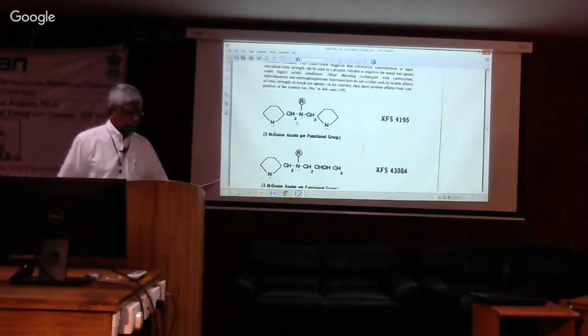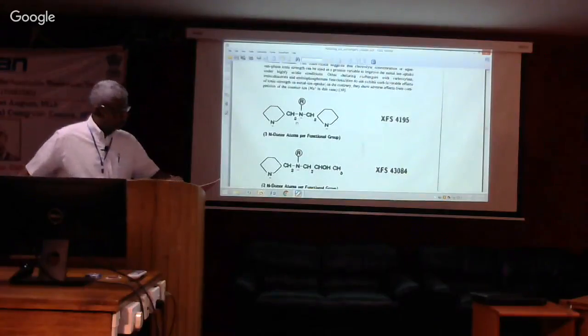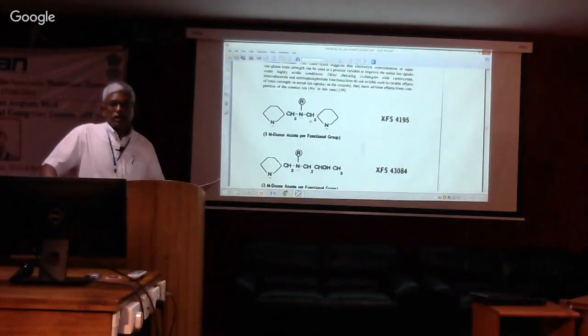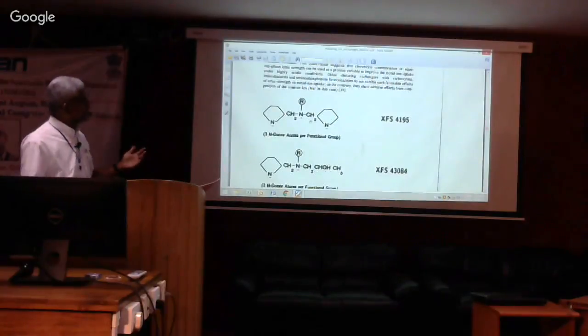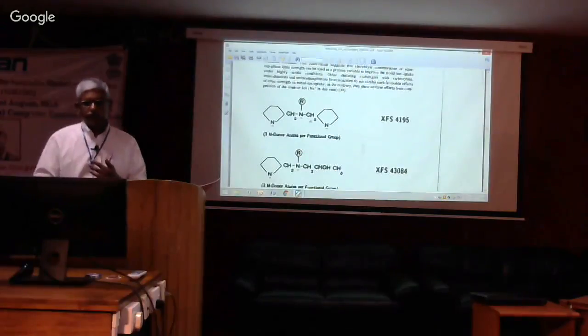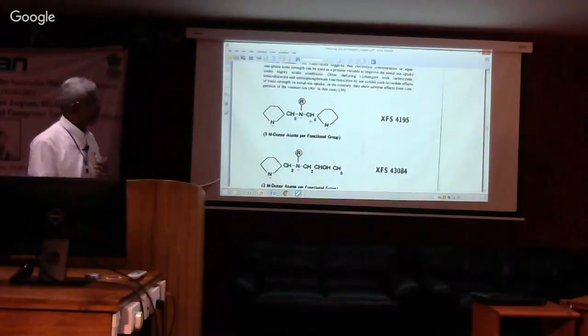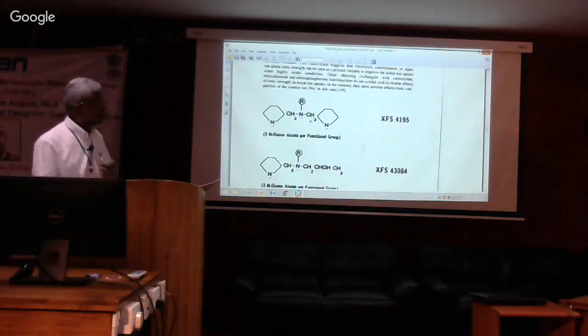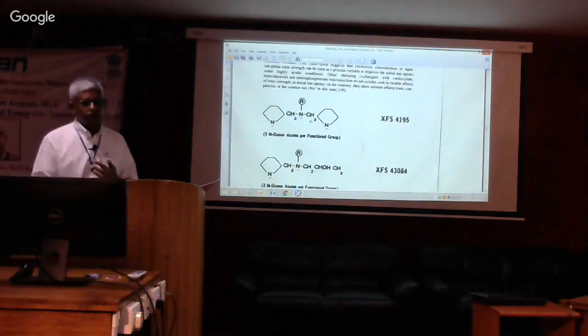Okay, so the point that I'm trying to make is that we have to understand our situation before we start the separation process. We have to look at the aqueous phase, what all is there, and in terms of heavy metal removal, what all ligands are possible. We have to model their ligands.